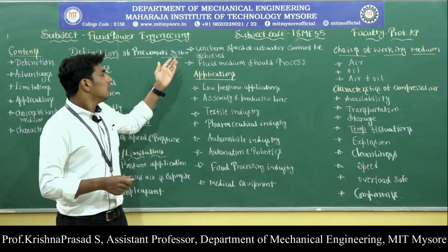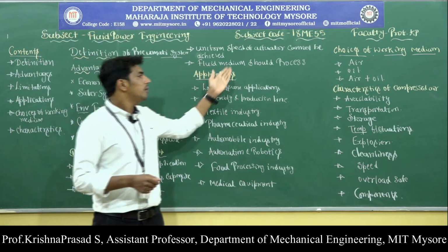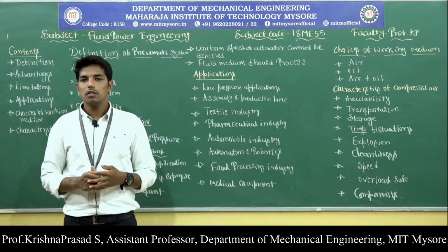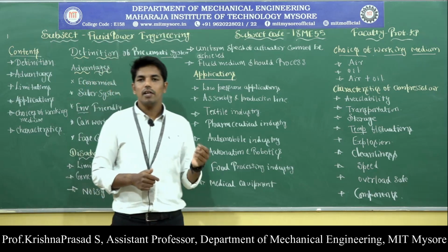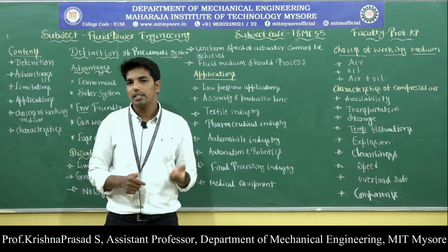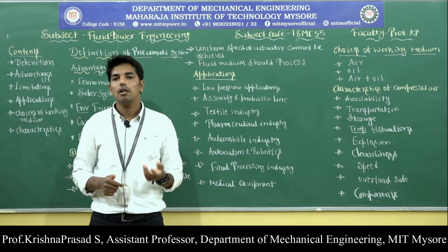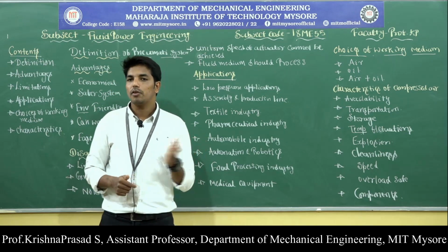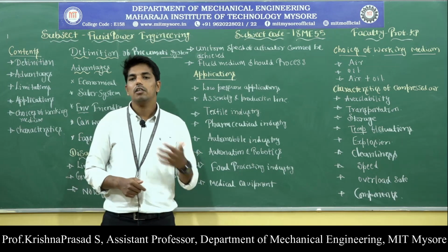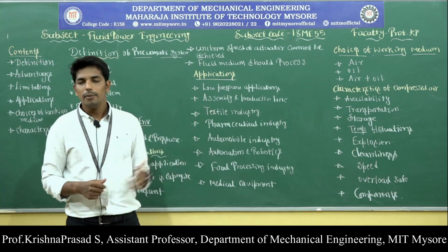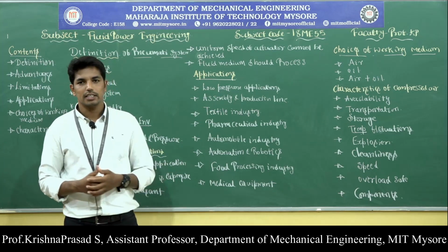Next one, very important, the fluid medium should be processed before use, because the atmospheric air we are compressing to very high pressure contains smoke, dust, dirt as well as water vapor. This needs to be removed, otherwise it will lead to problems like wear and corrosion. That is the main disadvantage in the pneumatic system.